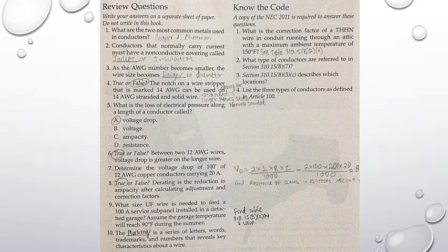So this is the allowable ampacities of a single insulated conductor rated up to and including 2000 volts. This is for a conductor that is going to be carrying the entire load on its own. It's not going to share the load with other conductors. It will just be one conductor for each leg, one for the hot, one for the neutral. And one of them is ungrounded, of course, one ungrounded conductor.